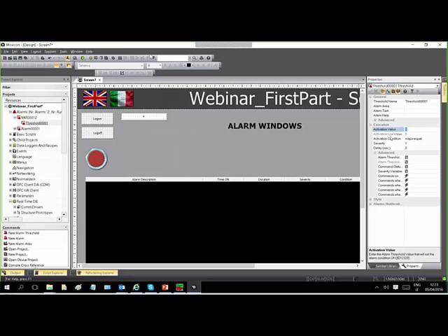So only one alarm. It will save me time to generate the alarms because I have a resource. Pack the alarm: I want to exchange only one variable, a word, a byte, and I want to insert in this variable. Each bit is a different alarm. These are the ways that you can use to generate the alarm.